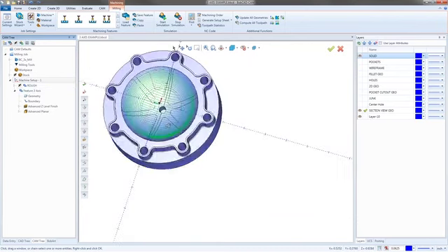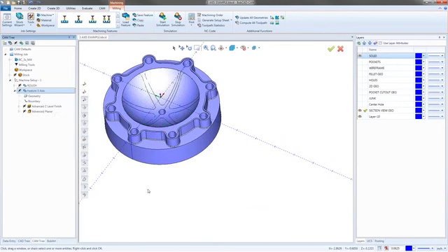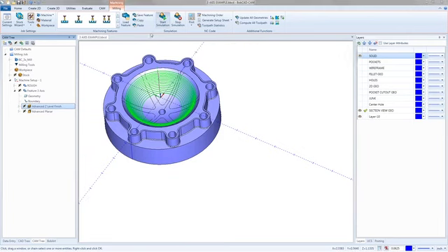Here we go. The toolpath is done. Now, like I said, I didn't go too crazy with the depth of cut and step over. We didn't go too deep. We got some toolpath. Here's the advanced Z level. The finish on this at 50,000, I can already tell you it's not going to be really great, but the fix for that is just giving it a better finish pass, a better depth of cut or step over. So let's go ahead and check this thing out.